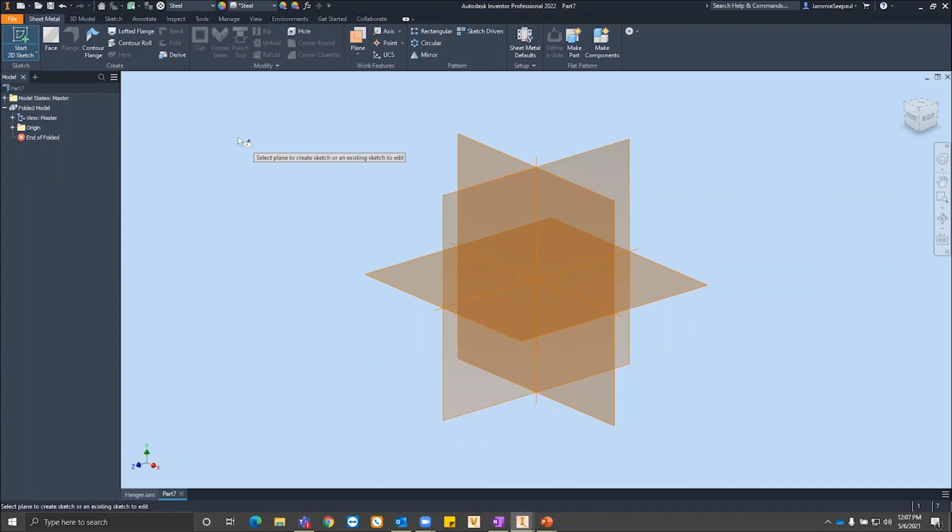Choosing the material that you're actually going to be using can affect your tolerances whenever you bend. There are many things that can affect your bend, especially how you're going to bend, what press brake you're using, what tool you're using, but it's good to have your material set correctly. That way the K factor can be accounted for. Okay, that's good to know.